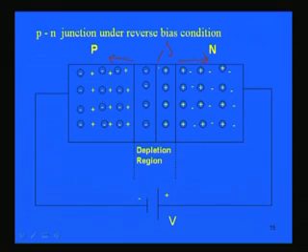As a result of that, more and more uncovering of the fixed or bound charges will take place, because these carriers will move away, they will be surfaced out. As a result of this, the depletion layer, the depletion region, will now be extending; it will be increased.